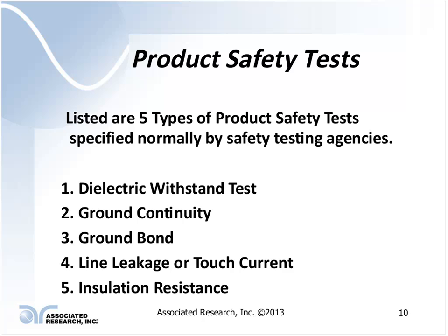But the dielectric withstand test is not meant to be a destructive test. This is a test that is done to verify the integrity of the insulation, to make sure that there are no faults within the insulation itself. And we'll talk about that as we go through this.